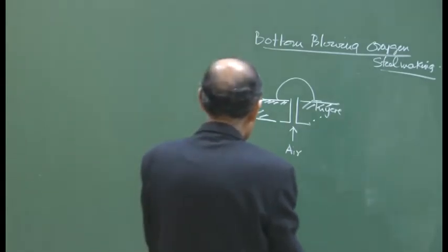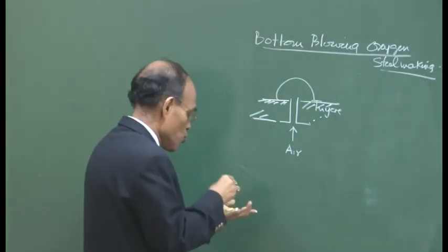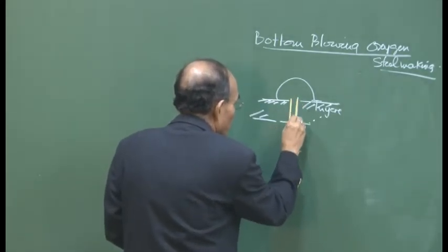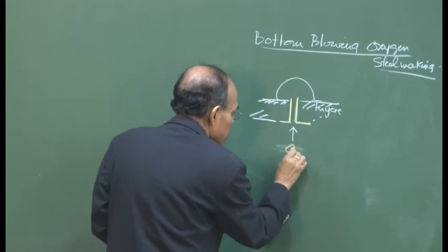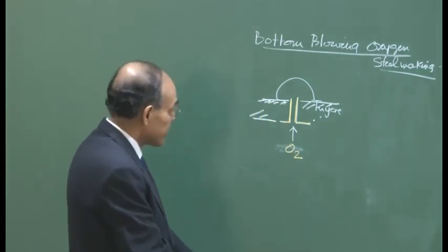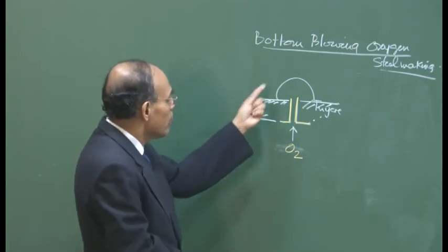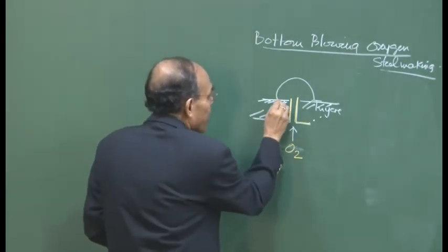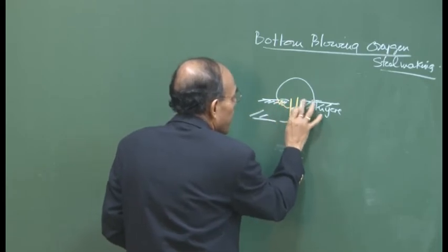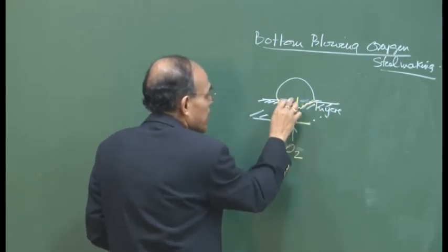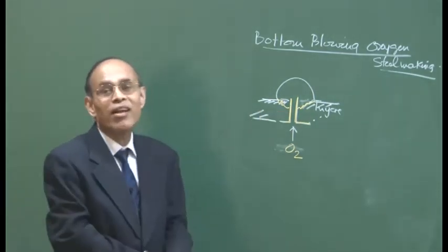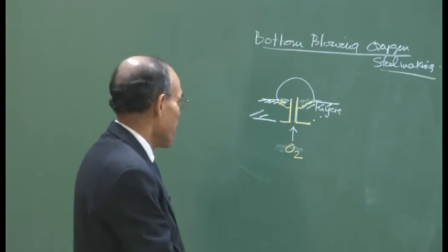I have mentioned that also. So, this shows you one tuyere through which oxygen is injected, and if you inject oxygen, you have a problem with local refractory erosion. The refractory will undergo erosion, exposing it to high heat, as a result of which the tuyere undergoes degradation very quickly.